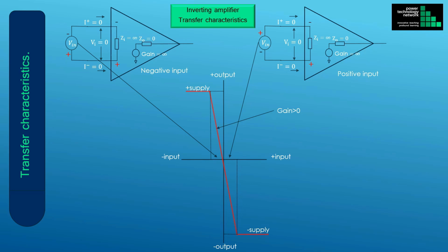It is worth noting that this representation is linear, meaning that the line is a straight line until it ends in the supply rails. In real life, this curve is not always linear, and the graph is not a straight line, making it nonlinear. This leads to distortion and the output is not an exact amplified representation of the input. When this curve is not a straight line, it means that the gain is not constant, but varies. As we shall show later, this effect can be minimized using feedback.